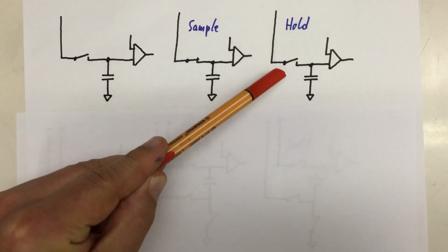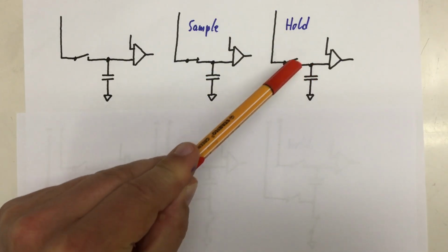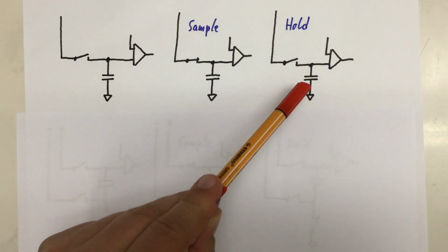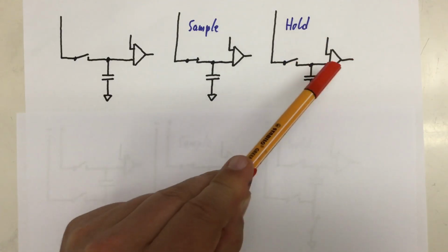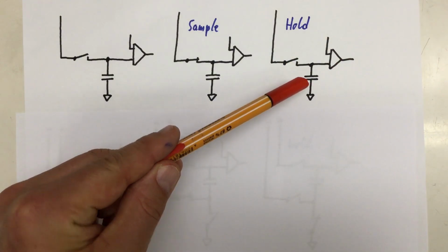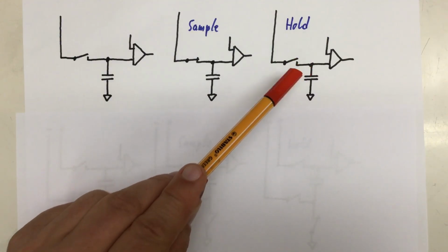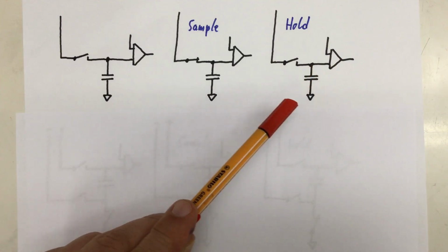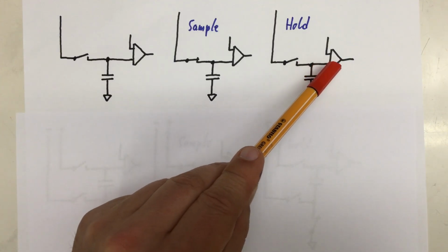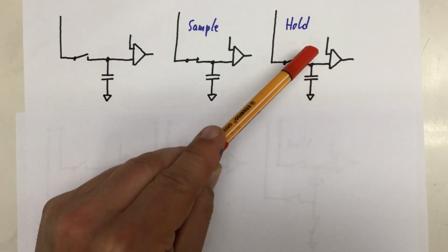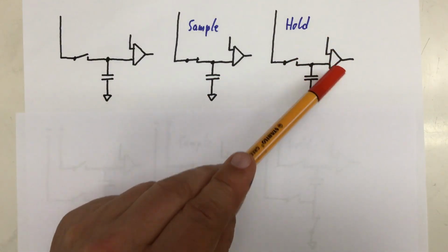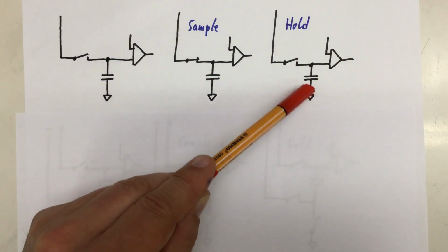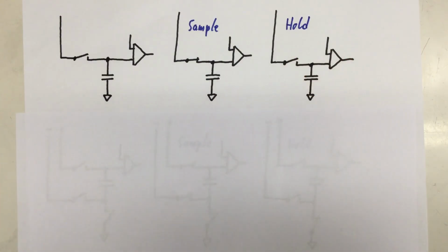Then the switching element is opened and the input voltage to which our capacitor is charged up can now be digitized. Side note: if you slow down the SPI clock, you make the analog to digital conversion longer and the capacitor has more time to discharge through the high impedance input of the comparator. And so you create a greater error.